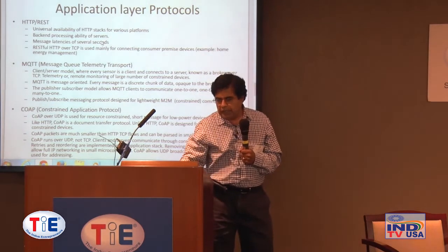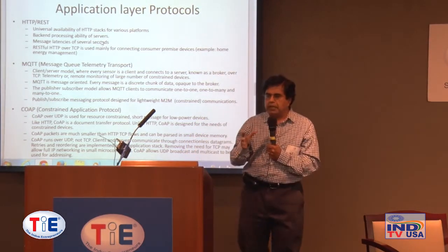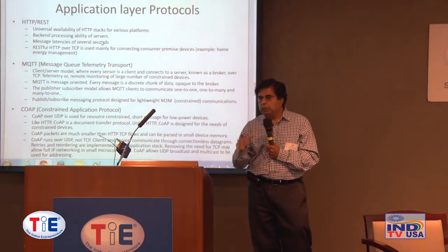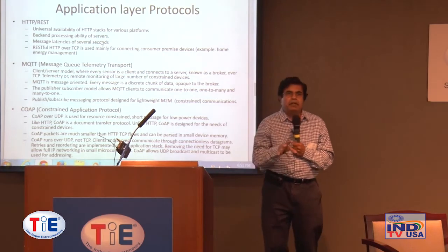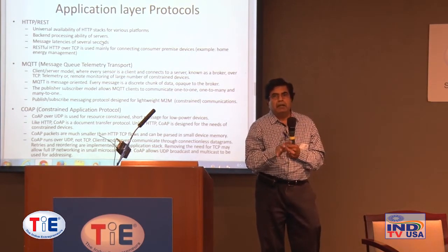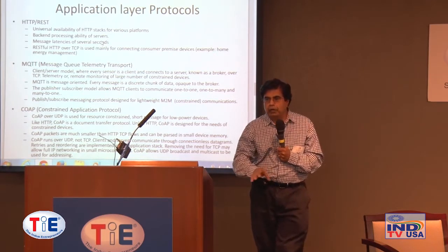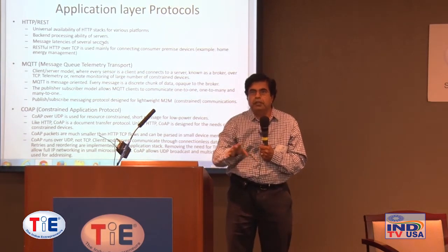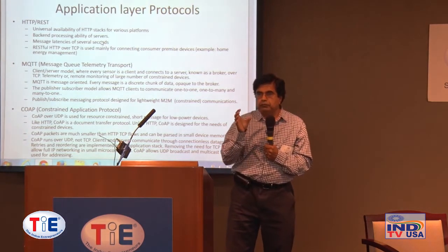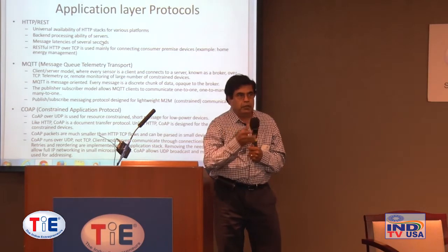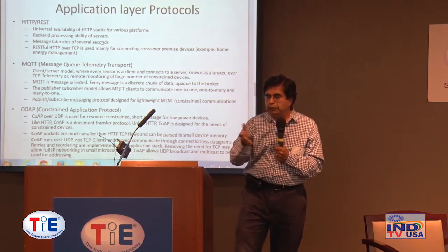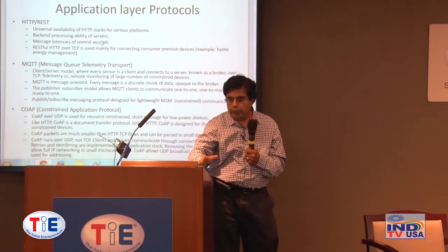So there are other protocols like MQTT and Constrained Application Protocol, which came about to look at constrained device requirements, so that a constrained device can run all the way to the server. This particular protocol can run with a very small amount of footprint, what we talked about in the SoC and other cases. So MQTT is a very popular M2M lightweight protocol.